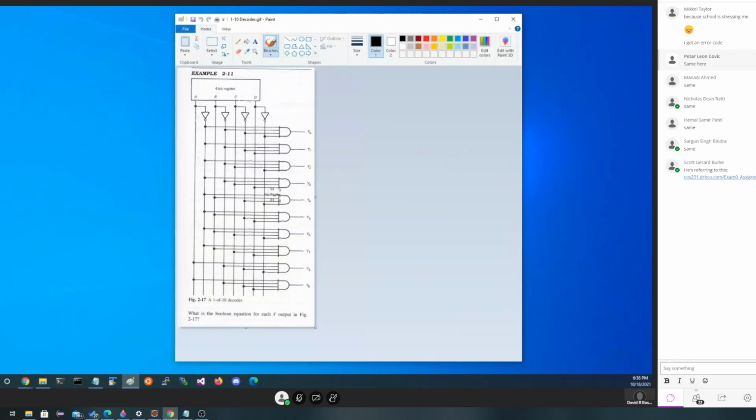So normally we would constrain the inputs here to stay within the bounds of 0 to 9, so we could select one of the outputs. Now, typical use of this in a microcomputer might be to decode an instruction. Let's say we have an instruction which we could store in 4 bits here, and then have each of these come on if that's the instruction we're currently trying to execute. Maybe it's a load, maybe it's an add, maybe it's a subtract, maybe it's a move, maybe it's a halt. Whatever those are, further logic over on this side could decode what it's doing, because you can imagine that the steps you do to do an add must be different than the steps you do to do a halt.